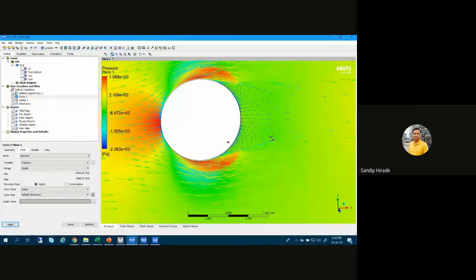That is how you have to choose your boundary conditions, and boundary conditions are again based on the information available before you are solving any problem. Suppose you know that your incoming flow is at some velocity or some pressure, so based on that you can choose that boundary.